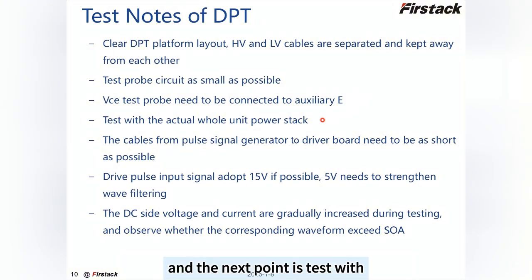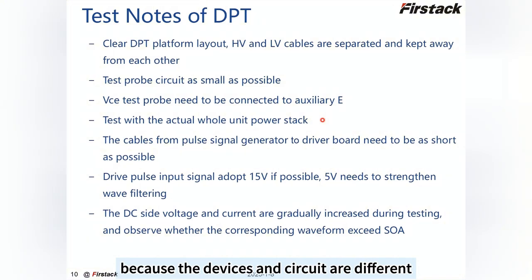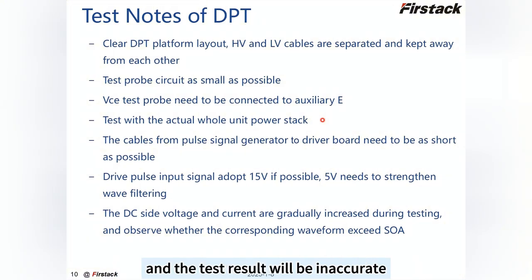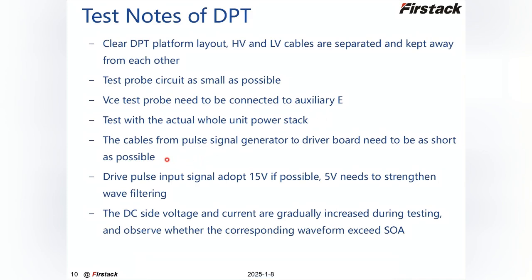The next point is to test with the actual complete power stack. If you just test the IGBT alone with peripheral circuits and then evaluate the performance of a complete power stack, it is not advisable, because the devices and circuits are different and the test result will be inaccurate.